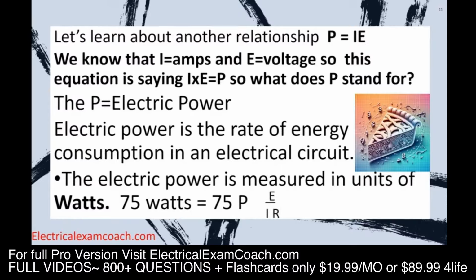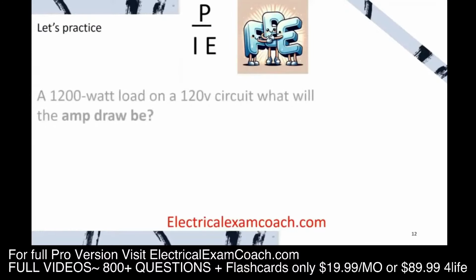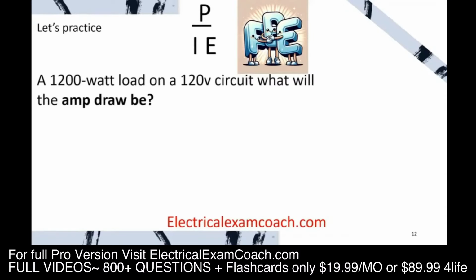Just like we set up our previous formula like this, we're going to set this one up like this. And I like to think of pie, P-I-E. Makes it easy for me to remember. And just like in the other formula, as long as we know 2 of the 3, we can always solve for the unknown. Let's give it a try. In our first scenario, we have a 1200 watt load on a 120 volt circuit. What will the amp draw be?